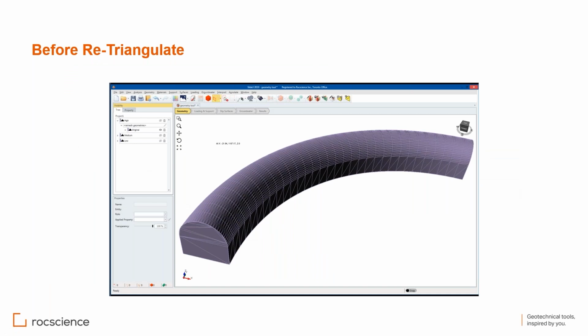Mathematically, if you want to create a surface in the 3D world or a volume, you need to use some kind of mesh, which is called surface mesh, and they are triangulations. They are triangles. These triangles are used to create your volume. They must have some features to be good, to be able to create a geometry.